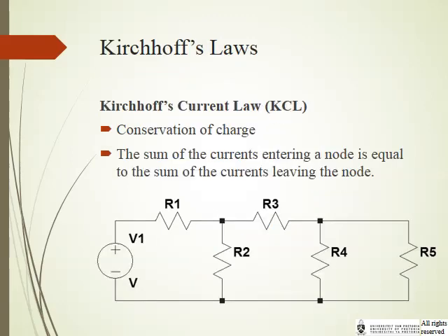Moving from Ohm's law to Kirchhoff's laws, and this hopefully will start ringing a bell. So what is Kirchhoff's? There's two Kirchhoff's laws. The one is the current law, and the other one is Kirchhoff's voltage law. What does the current law state? So first, let's just look at Kirchhoff's current law. Here we're looking at the conservation of charge, and it says that the sum of the currents entering a node is equal to the sum of the currents leaving the node.